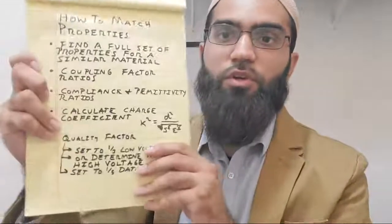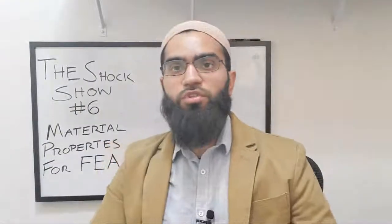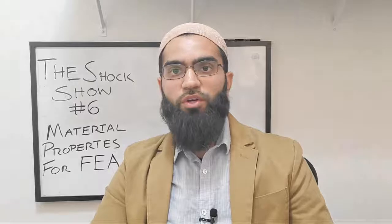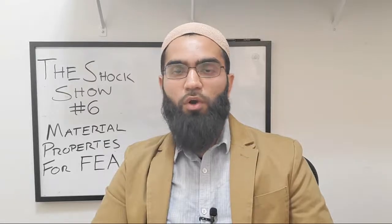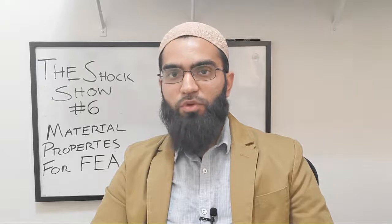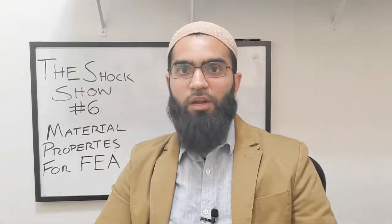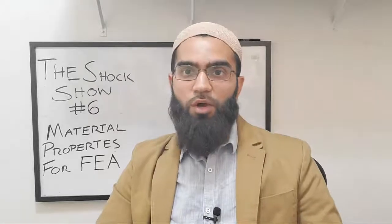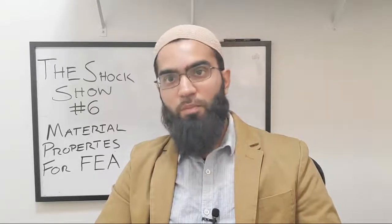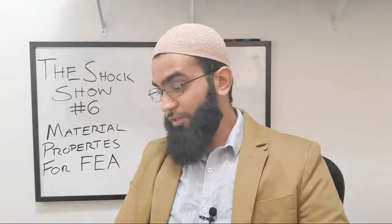The other thing you can do is determine the quality factor at high voltage. The way to do that is using a constant current frequency sweep across the resonance. If you have your system set up, you can do this using an impedance analyzer. If you have a series resistor, it's a little bit more complicated. This is a topic I'm going to get into in videos to come. I'm making videos every day, so we're going to get there sooner than you think.